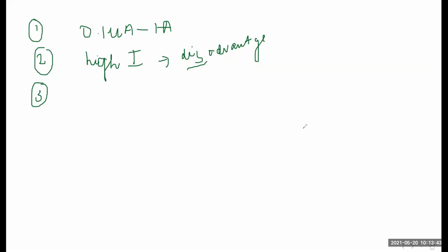Why is Kelvin double bridge used to measure low resistance? See, I taught you some errors also, significant errors. So actually, in measuring low resistance with any other device, some significant error in reading occurs. So hence to overcome that error, we use Kelvin double bridge. So this is one of the advantages of Kelvin double bridge.